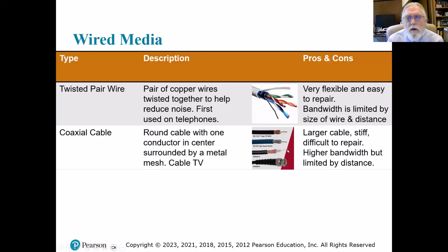You see there's the center conductor, that copper, kind of orange color, and then a white insulation, and then there's a braid that's around it, and then the black is the jacket. You have to get it to that condition before you can attach the connector. It goes on the end. So it's a little bit more of a challenge to replace a connector, or if the cable gets damaged and you want to cut the damaged part out and put in some replacement connectors.